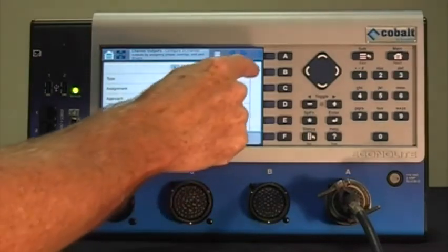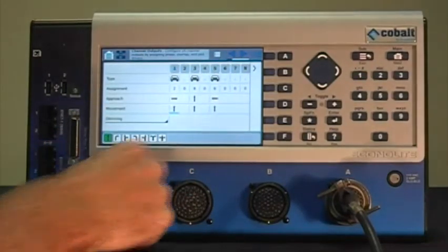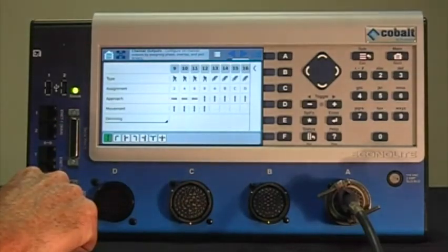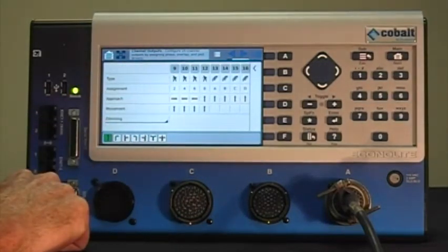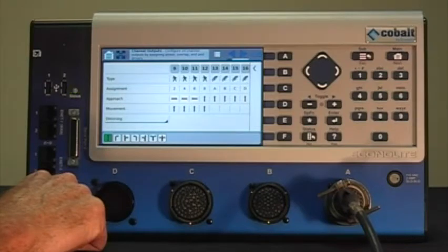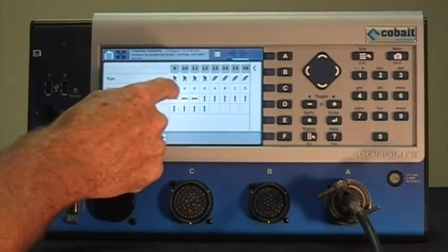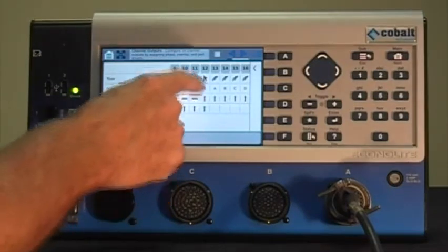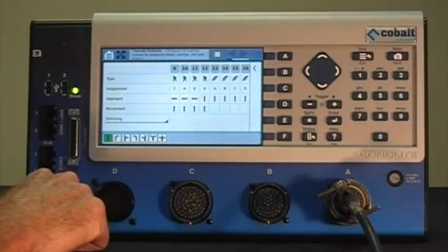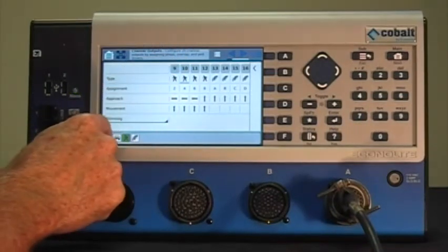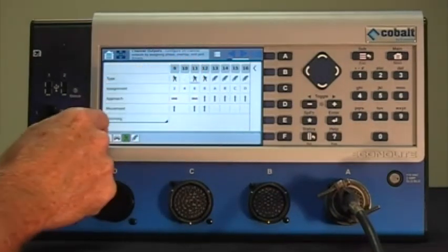And there's a second screen. You'll notice an arrow on the right side here. That's for the rest of the channels. There's 16 channels in this controller. The first are typically vehicles, and the rest are pedestrian and overlaps. If you recall from the diagram, we're going to have channel 9 set to PED 2, so that's already okay, and channel 12 set to PED 8, so that's already good, but we're not using these others. So as we did before, let's remove those.